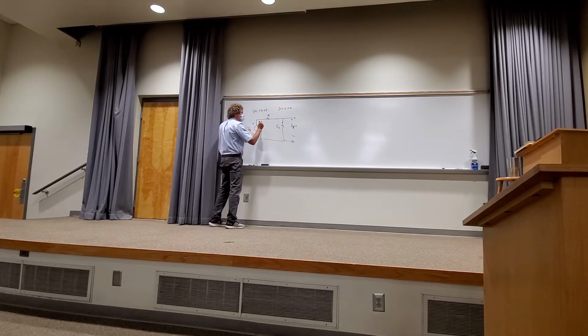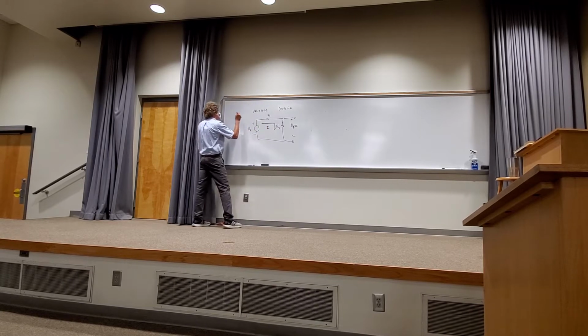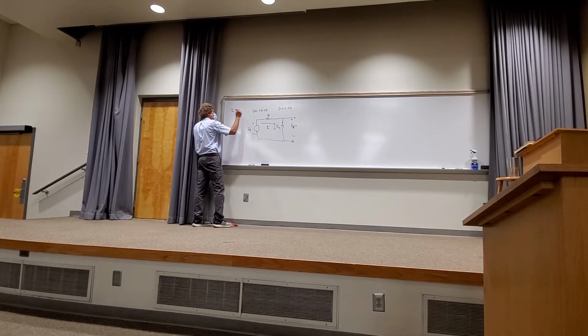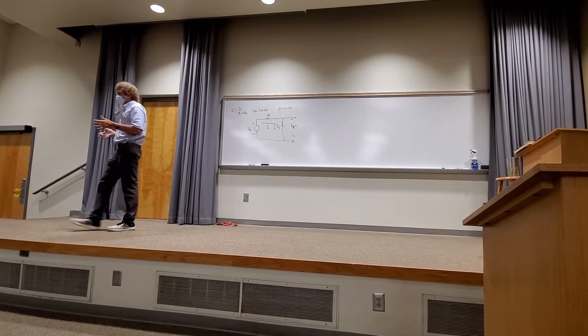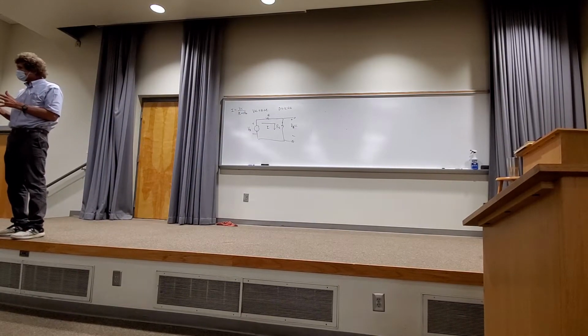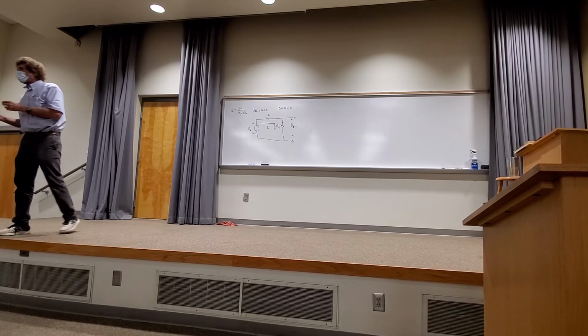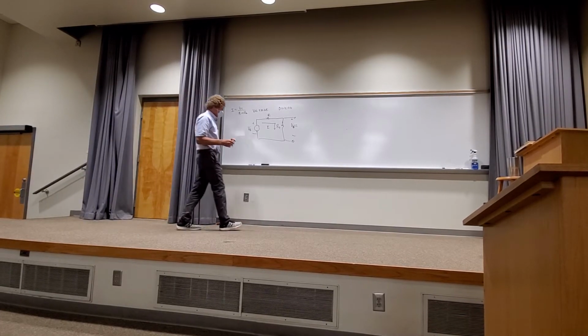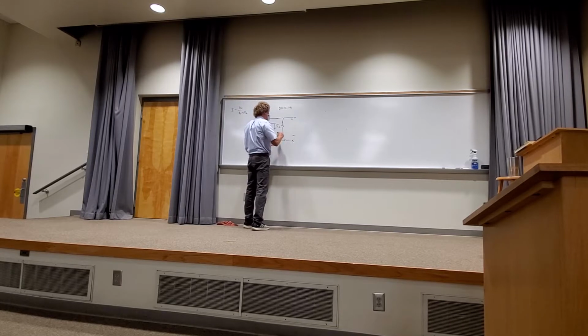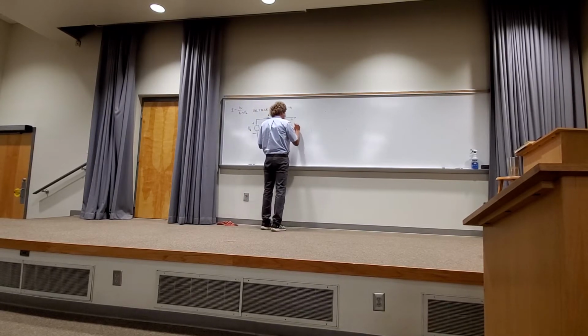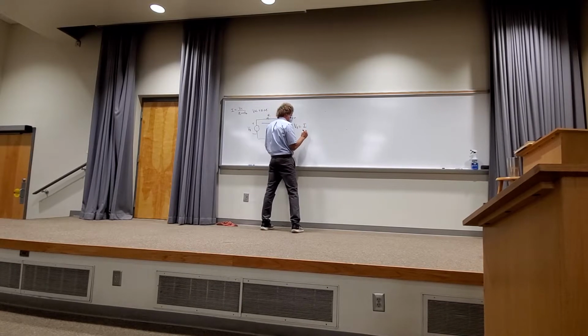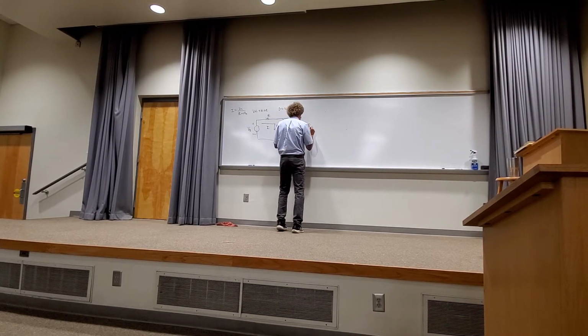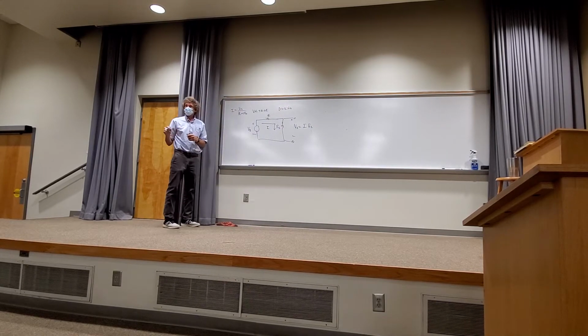That means this current flowing here, according to Ohm's law, I can get by taking Vs over that single value, which would be R1 plus R2. Take a look at that. Do you all agree with that? I've combined R1 and R2, in my mind, sort of, put it up there, and made that statement. Do you all agree with me? Yes, sir. Now, if I have a current through any resistor, then this voltage can be gotten by taking that current through it times the resistor R2, right? You agree with me? Correct, class?